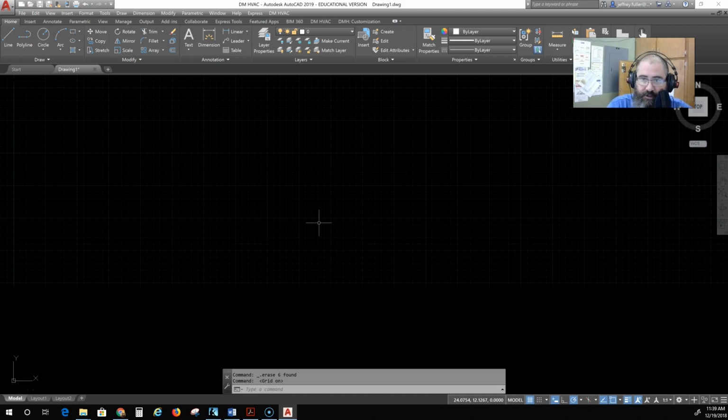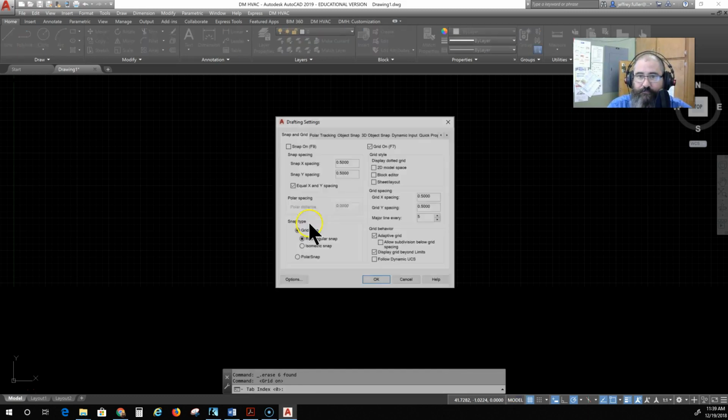But I'm going to keep those on. If you can see them, great. If you can't, don't worry about it, because I'm going to turn something else on in the status bar that's right next to the grid icon, and this one's just like a bunch of dots in series, and it's called snap mode. Now this turns grid snapping on and off, just the grid snapping. You can also click on this arrow next to it and change some of the settings regarding that snapping. If I click on snap settings,